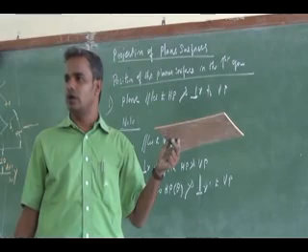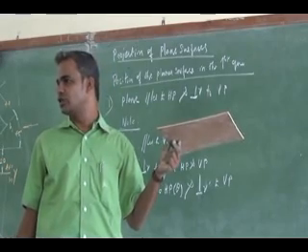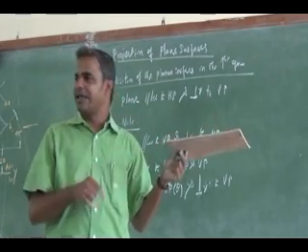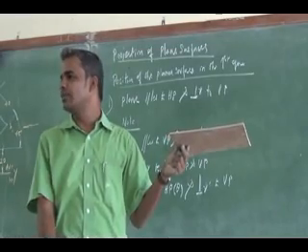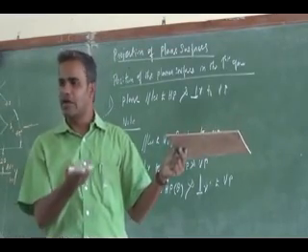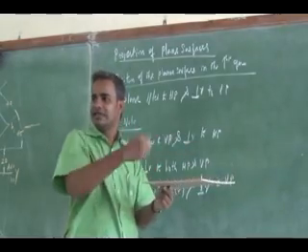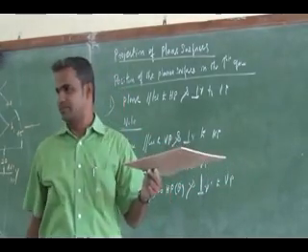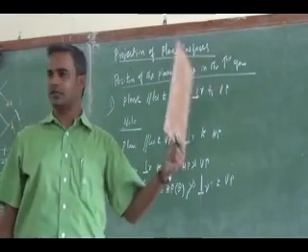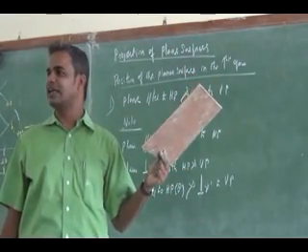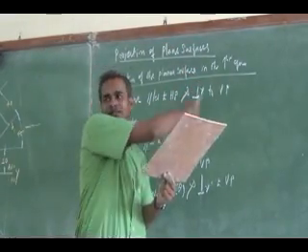So if I draw it parallel to the horizontal plane, where can I draw the true shape? I can draw the true shape on the horizontal plane. I will get a front view as a straight line, and that front view length is the same. So if I tilt it like this to the 30-degree inclination, I will have the same front view length.